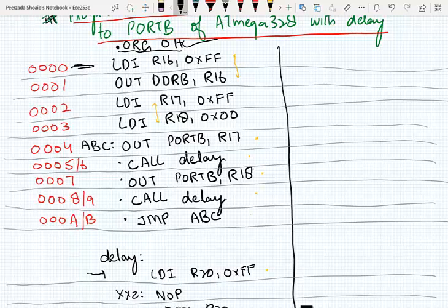The next instruction, then this, all these will be in sequential order, because the program counter increments itself after execution of the instruction. It always points to the next instruction to be executed. And in case of jumps or calls, the program counter is fed by the processor some other value depending on how we are calling or how we are jumping.